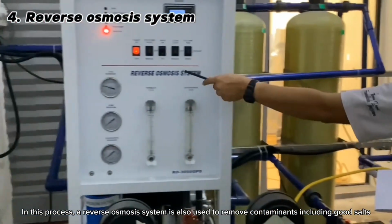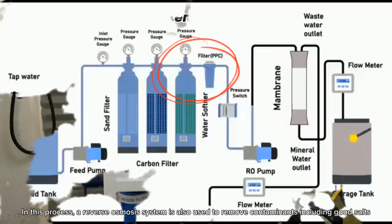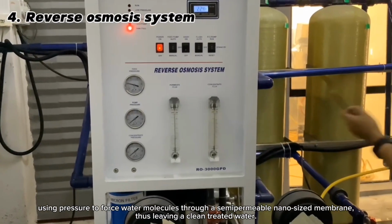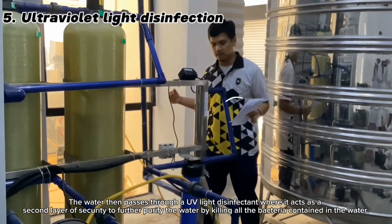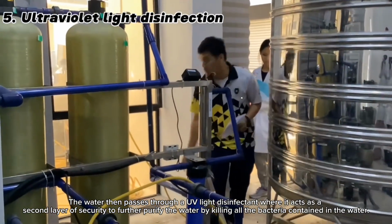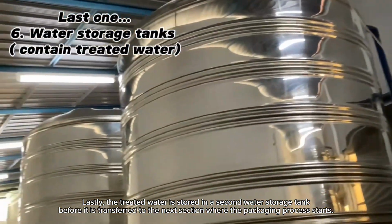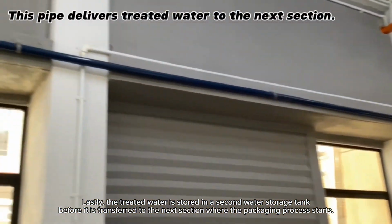In this process, a reverse osmosis system is also used to remove contaminants including good salts, using pressure to force water molecules through a semi-permeable, nano-sized membrane, thus leaving clean treated water. The water then passes through a UV light disinfectant, which acts as a second layer of security to further purify the water by killing all the bacteria contained in the water. Lastly, the treated water is stored in a second water storage tank before it is transferred to the next section where the packaging process starts.